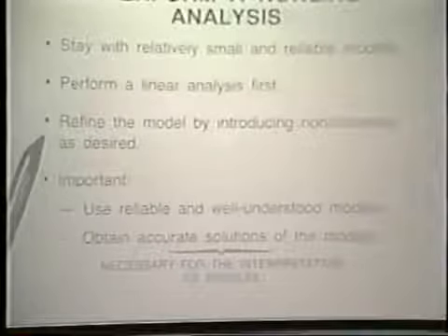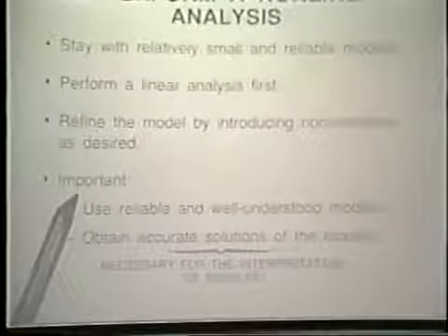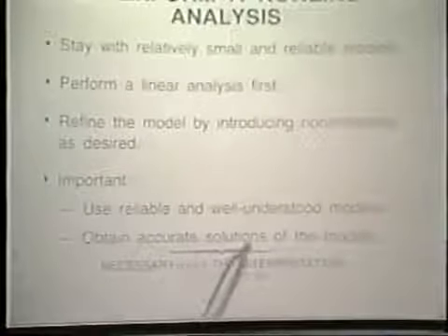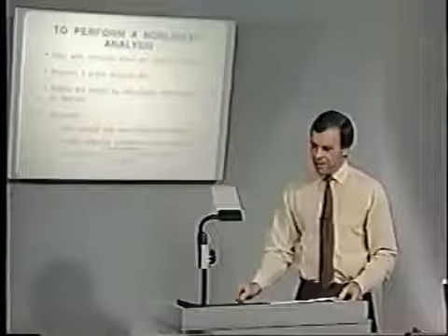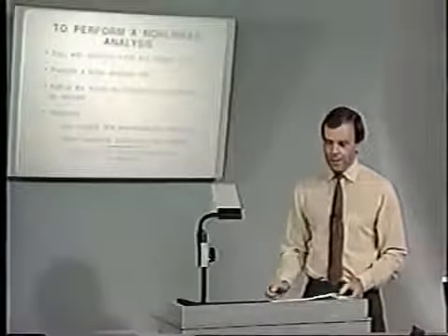I will show examples in this course, particularly related to this item here. It is very important in my view to first do a linear analysis and only then go on to a nonlinear analysis. As I mentioned already, we want to refine the model by introducing nonlinearities as desired, and once again use reliable and well understood models, obtaining accurate solutions of the models. This is very important for proper interpretation of the results.